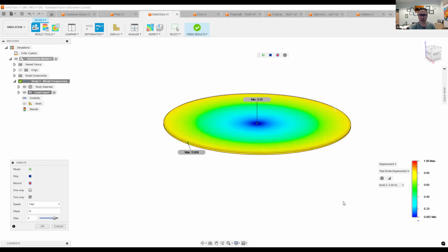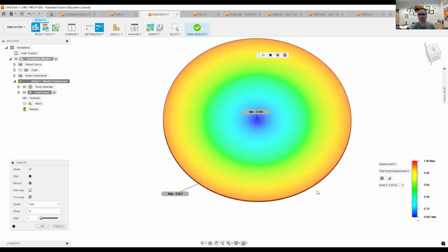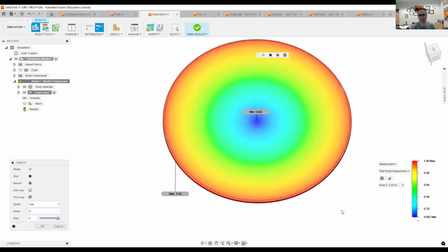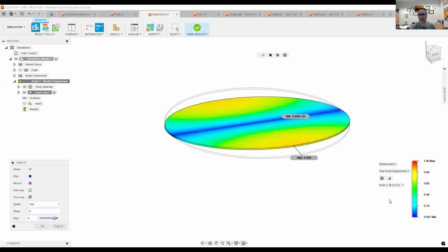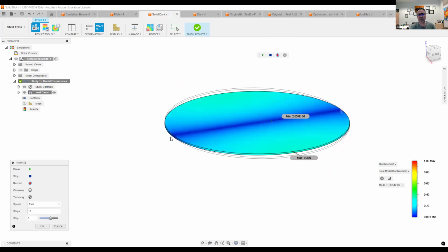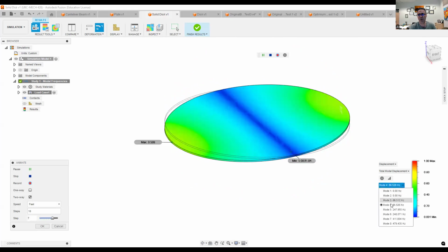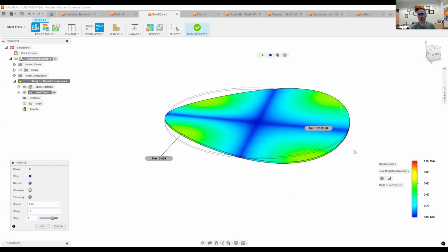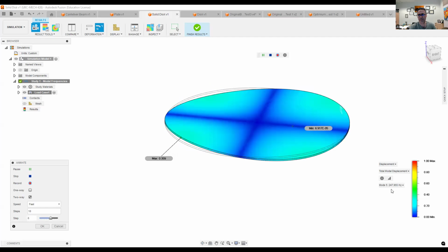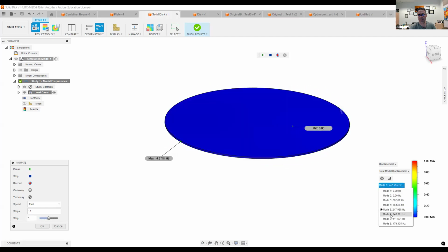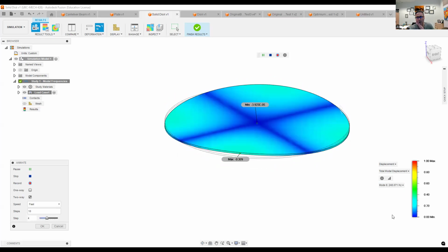Second mode, my mistake, is again another rigid body mode. It just shows the in-plane motion. So we ignore the first two modes. So the third mode, which is the actual first mode, is one nodal, and perpendicular to that one nodal. Let's go to the fifth mode, a two nodal, and the sixth mode is like that.